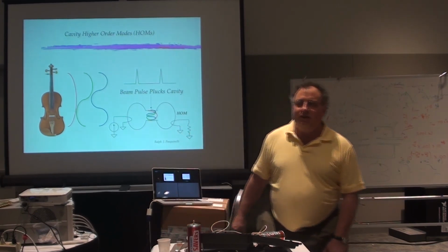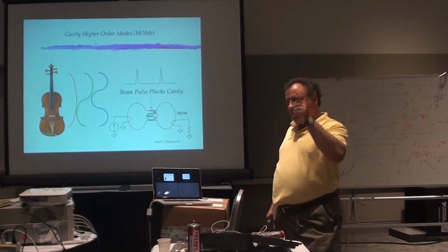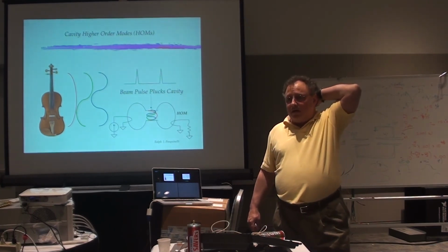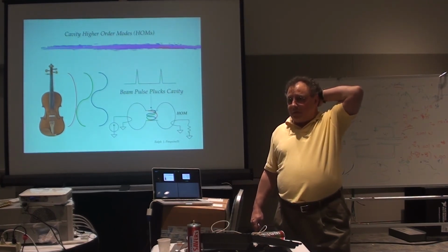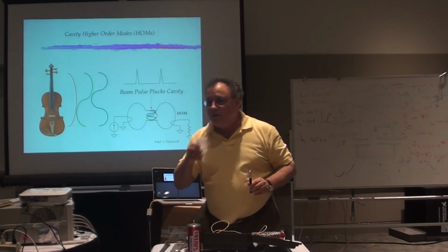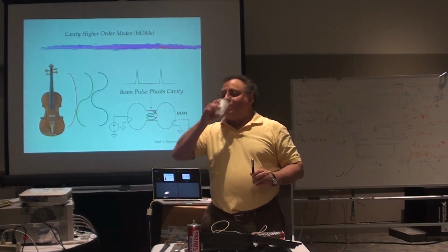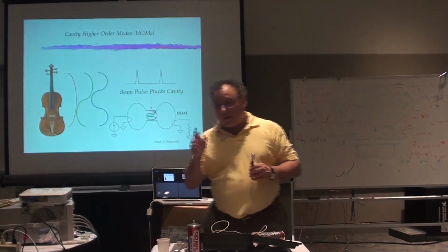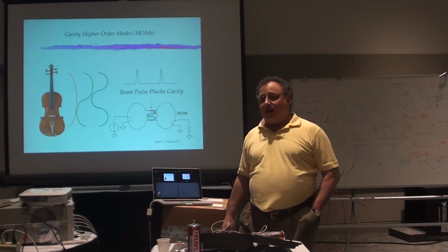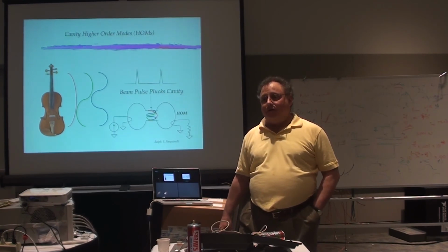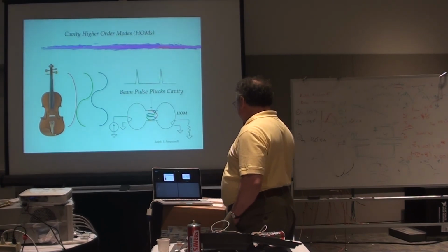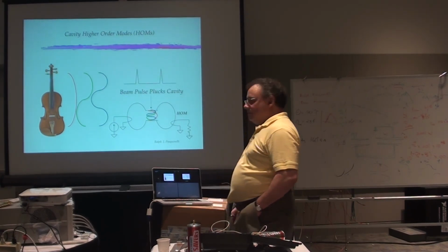They're not doing it. They have a pretty broad bandwidth. I mentioned this yesterday: we made a specification that all our higher order loads have to sit 5 megahertz away from our beam machine lines. And our first cavity comes up and the higher order loads are right on. And you guys are going to test every cavity too, right? This tells you that you've got to really pay attention to the manufacturing, because just a simple misshape in the cells pushes the higher order loads right into the machine lines.